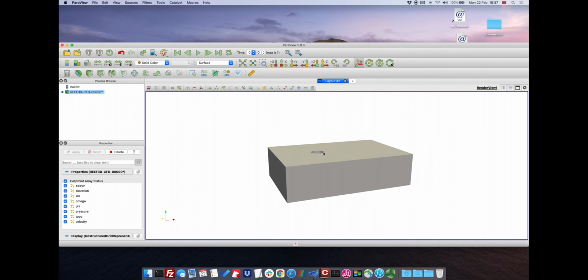All right. First, I will show you how to use the visualization of a slice. On several occasions, a 2D plane along the x-axis is the most interesting plane, at least in this case. Say, for example, we want to visualize a slice that is running along the center line of the tank, which intersects the cylinder in its center too.